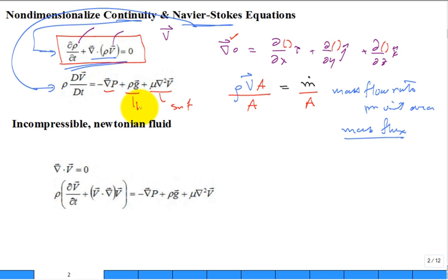This will be a body force, and this will be a surface force. But the surface force from the pressure is normal to the surface, and for the viscous term, it's a shear force to the surface. So these are all like the sum of the F's. And then what does it result in? The time rate of change of momentum of the system. So it can be swept in or swept out.